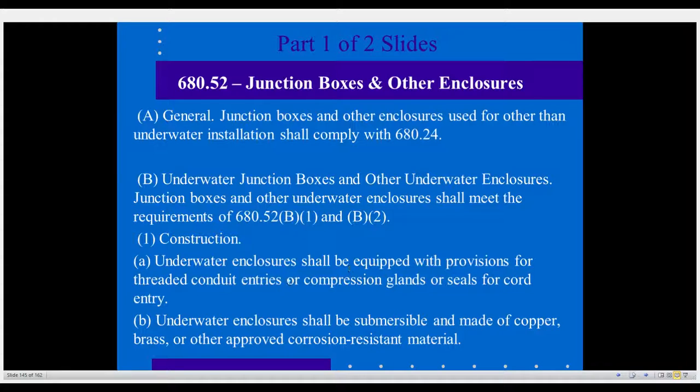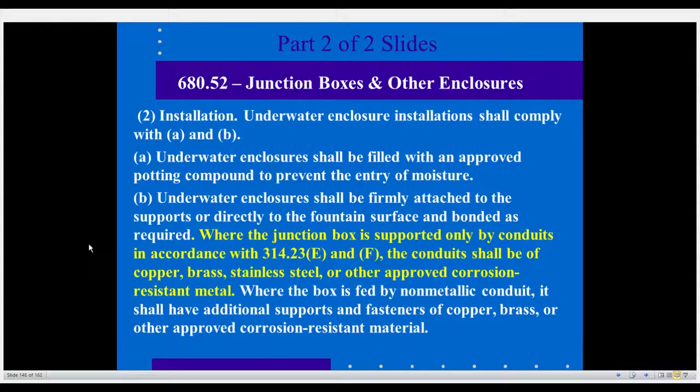Okay, so I've got to make sure I have that part of the construction. And the second part says underwater enclosures shall be submersible and made of copper, brass, or other approved corrosion-resistant material. Okay, so we have that application that we've got to deal with. All right, so that's the B1. Now the